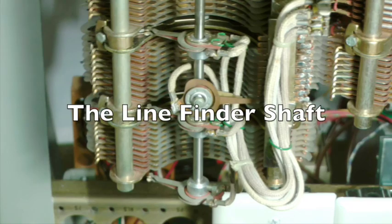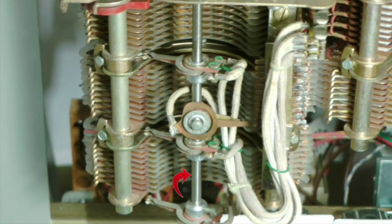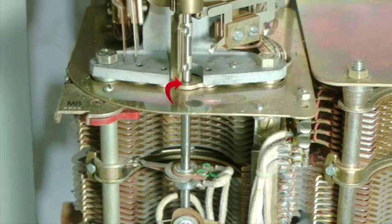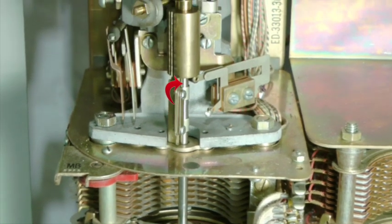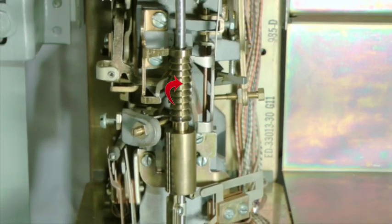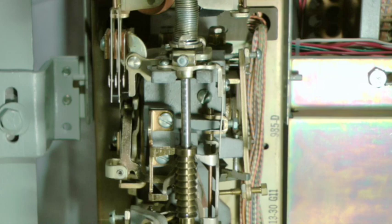We'll come back to the wipers shortly, but first we need to talk about the line finder shaft. The shaft is a 12.5 inch long by 3/16 inch diameter steel rod that is positioned vertically in front of the main parts of the switch. The shaft has a fixed vertical axis, which is constrained by its insertion through 2 vertically aligned stationary bearings.